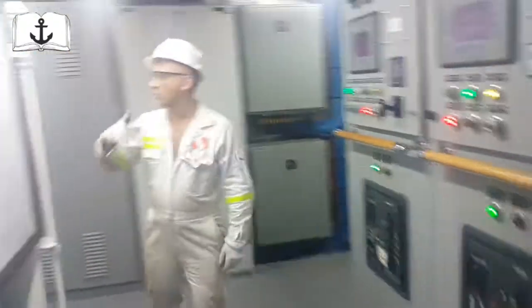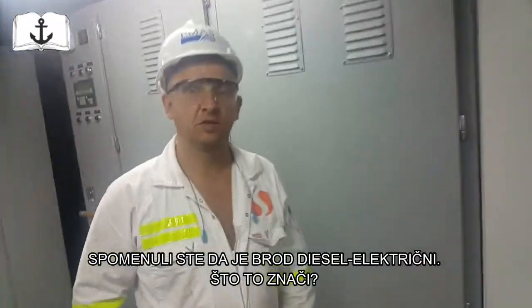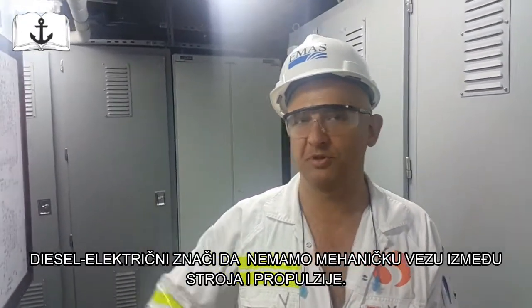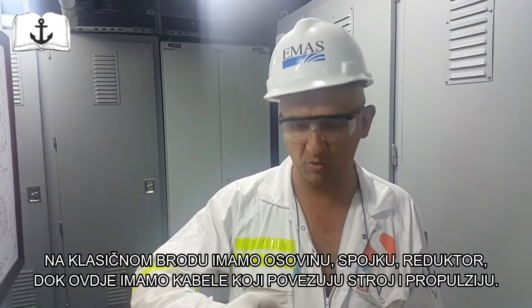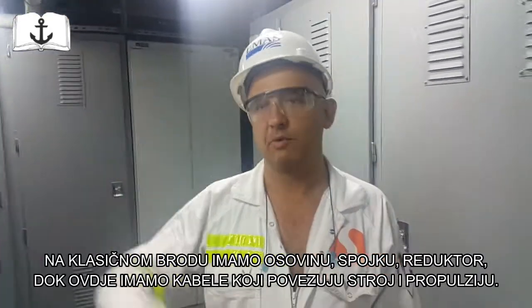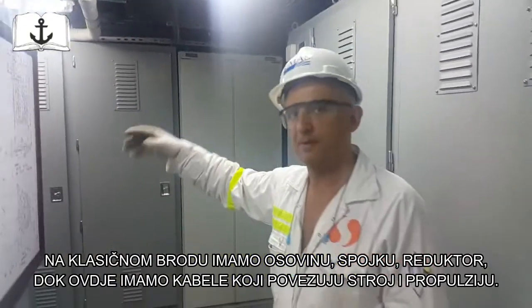Now maybe we can go here also. You mentioned the vessel is diesel electric. Can you explain that? Diesel electric means that we don't have a mechanical connection between the engines and the propulsion. On a conventional ship you have the shaft, or a clutch or gearbox or whatever. Here we have a connection between the alternator and the engine, with a cable going to the propulsion.